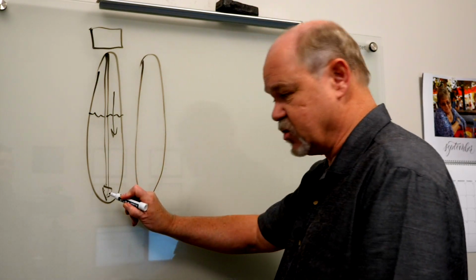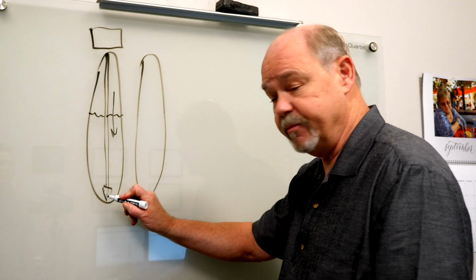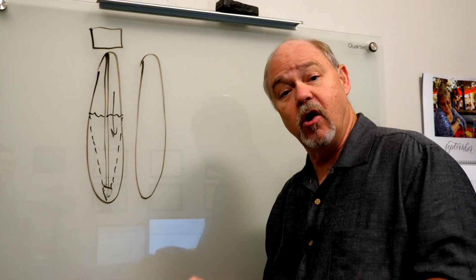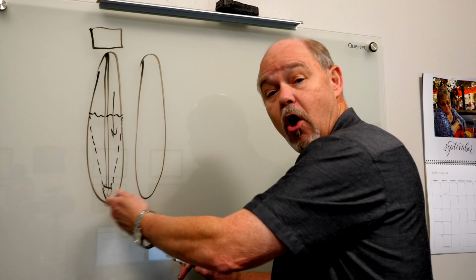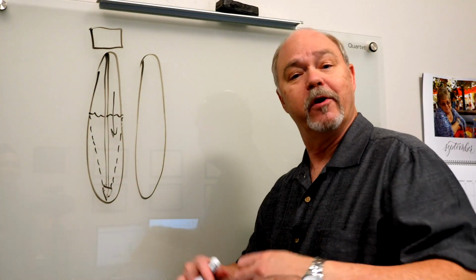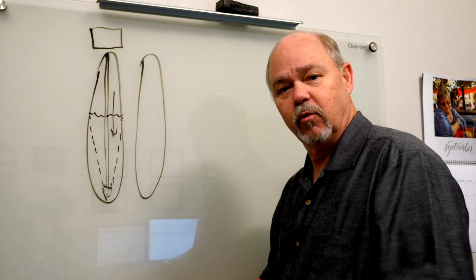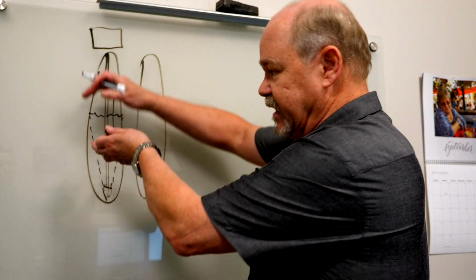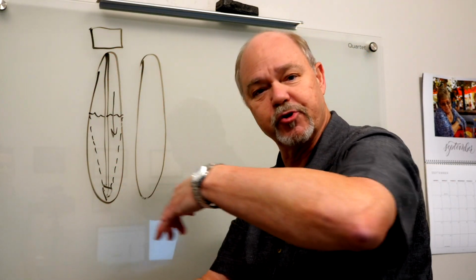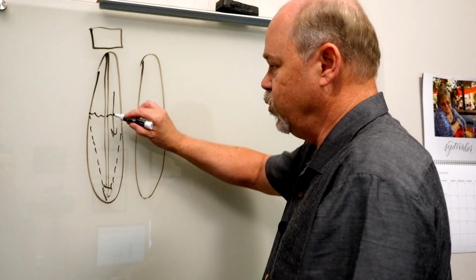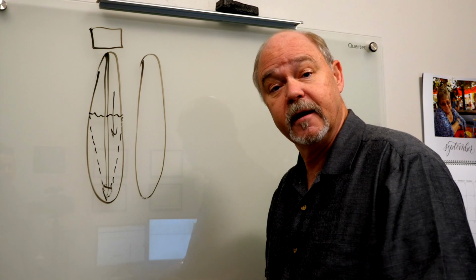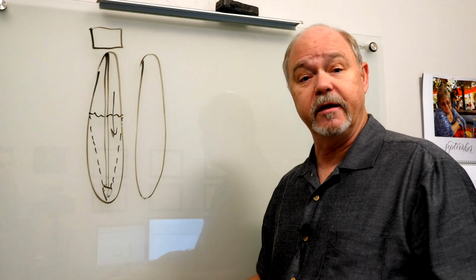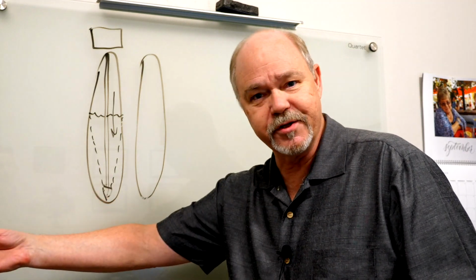But what happens, since it's all got to go through this little basket at the bottom, is we end up with water flow that goes right to that basket. And ultimately, we're not making use of all the media that's in that tank. So periodically, we've got a backflow or backwash. We have to move water in the opposite direction down the riser tube so that it lifts that media bed and stirs it up and re-stratifies it so that we can get all the media into play. Also, when it backwashes, it's going to put 30 or 40 gallons of water down the drain. The bigger the system, the more water to the drain.